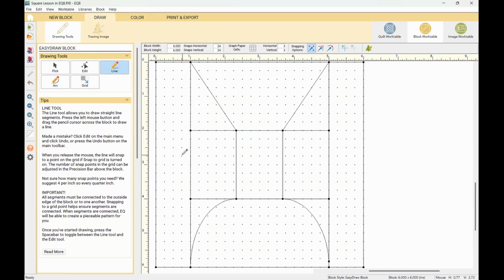I think if you have it snapped to nodes, sometimes when I draw the line, I try to actually go a little ways past the line I'm connecting to, to make sure it's snapped to the line. Yeah. Okay, so that's a good point, Carmen. If you draw a line and you really want to make sure it crossed that other line, you can do this too. You can start out on the far side of this and go all the way across like this. And when you go to color, it's going to get rid of that extra.